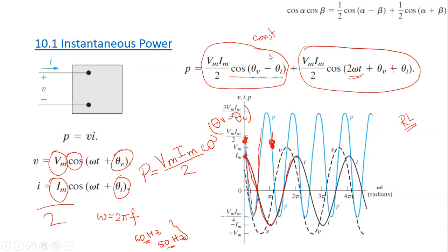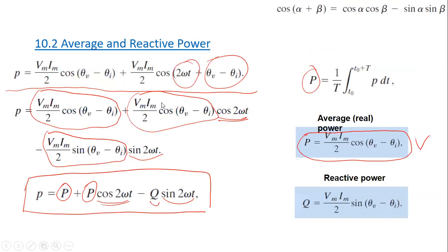You don't need to go through this mathematics, and you don't need to do the integration. You just need to apply this formula. But why are we discussing these formulas now? Because we need to understand how we came to this formula, and how is very simple. We integrated the instantaneous power over one period and divided this integral by the time of that period. So this is the average power.